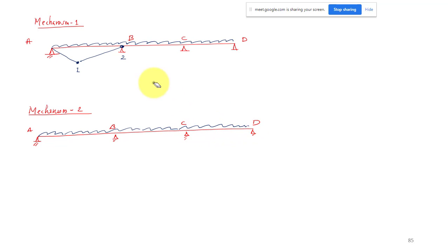Here AB will be like this only, you can treat it like a propped cantilever. When you come to BC, that will be similar to a fixed beam. For both sides we have the moment and we have the loading here, so three plastic hinges are possible.